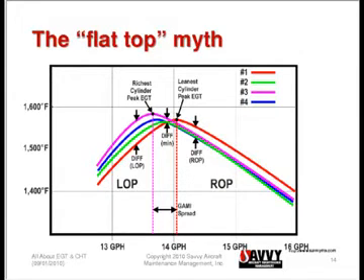What we're really interested in is what's called a GAMI spread. That is, the difference in fuel flow between where the rich cylinder reaches peak EGT and where the leanest cylinder reaches peak EGT. Because in a perfectly balanced engine, all of the cylinders would reach peak EGT at exactly the same mixture. That's what we really strive for.